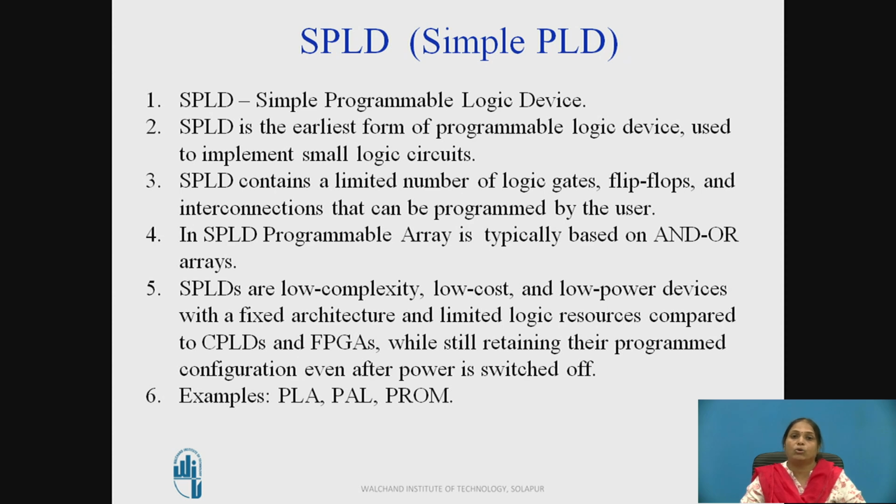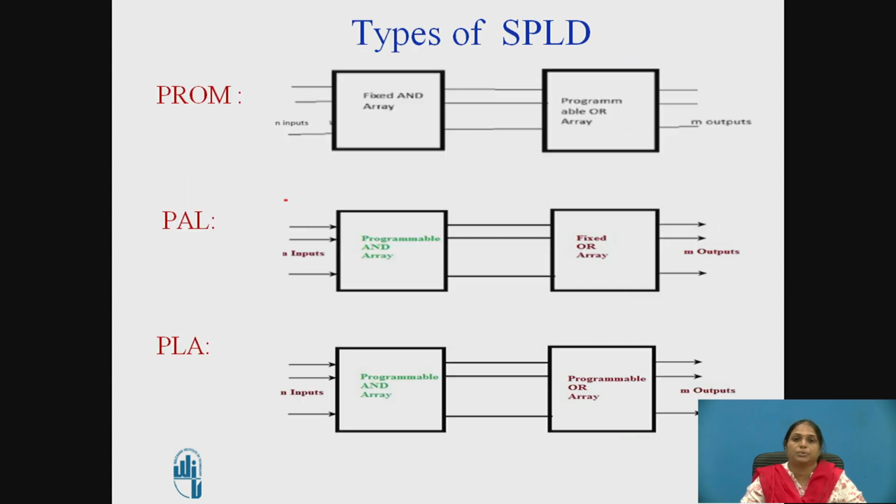SPLDs are low complexity, low cost and low power devices with a fixed architecture and limited logic resources compared to CPLDs and FPGA, while still retaining their programmed configuration even after the power is switched off. Examples, as discussed earlier, are PAL, PLA and PROM.